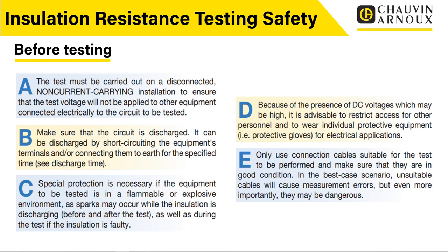Now, we might be at one end, fine. We're connecting up, we're testing at one end of the cable. There could be somebody connected, leaning on something at the other end, or especially if we're testing to earth parts, we could actually be applying that voltage to any earth part within the premises. So somebody could be touching a water pipe, somebody could be touching a tap, somebody could be in a bath, and we're carrying out this test. Obviously, we run the risk of giving people electric shocks.